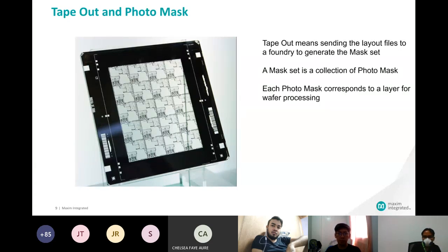So if there are more IC designers trying to design something that's kind of new, instead of spending $250,000 for a full mask set, if there are 20 projects trying to do that same new technology, you spend a $250,000 mask set, but on 20 wafers, 20 designs, 20 different parts.